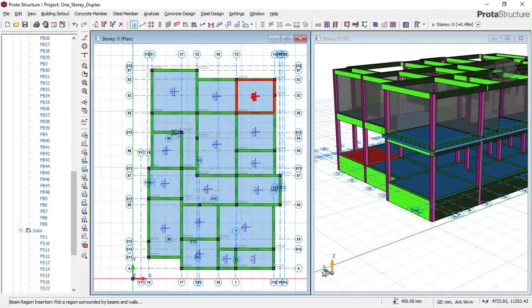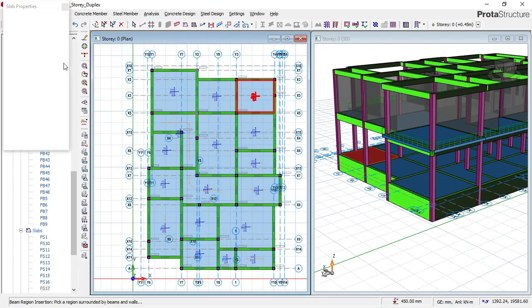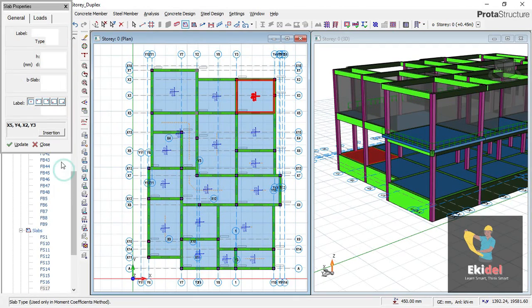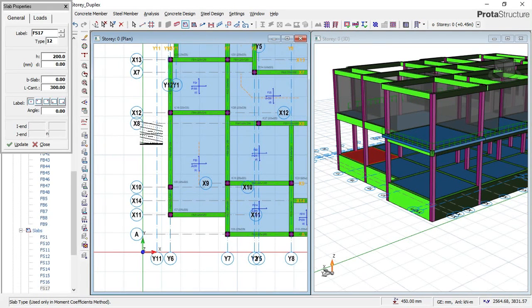Okay, so right now we will go here, the same place, slab, and click on slab. Now on this place, one of the dialogs appears. I will have to choose type 2F, because this type 2F is for cantilevers. Now I want my toe length, which is the cantilever length, to be 500. That should be your minimum that you should use, 500. You can go as far as using 800 if it is failing.